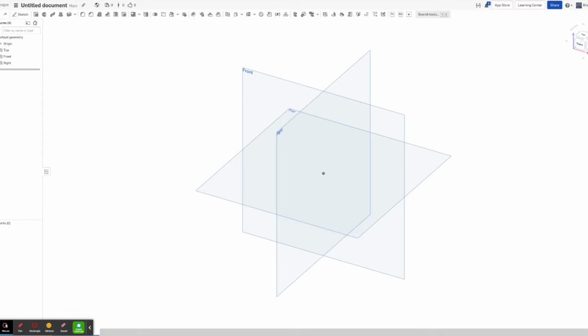I'm Brian, and today I'll be showing you how to use the Intersect Extrude command. The Intersect Extrude command is important because it allows you to take two extrusions and only keep the intersection of those two extrusions. And this allows you to create some more complicated shapes.